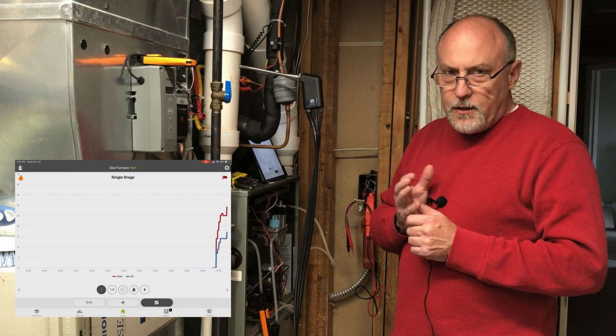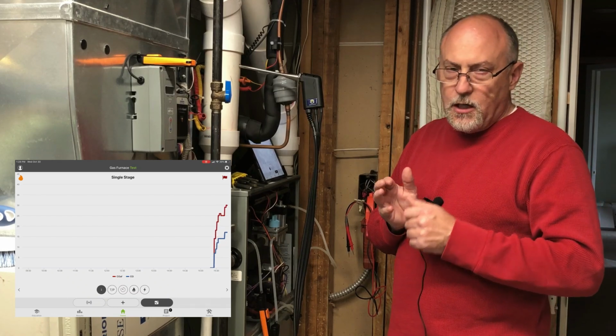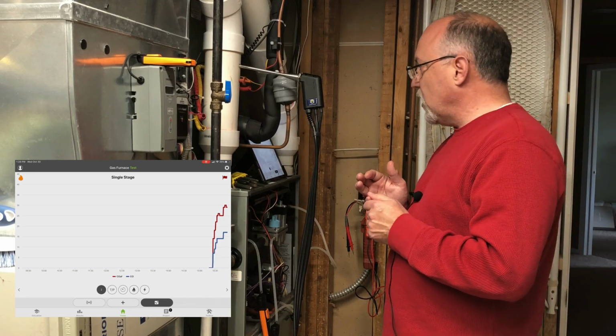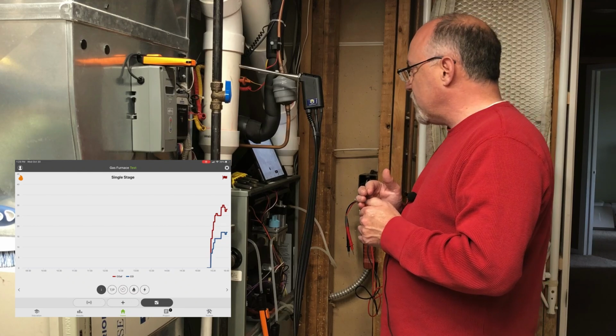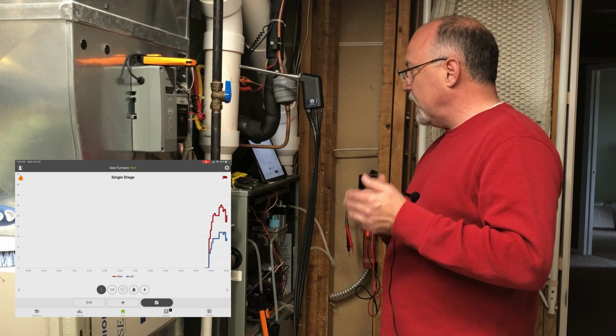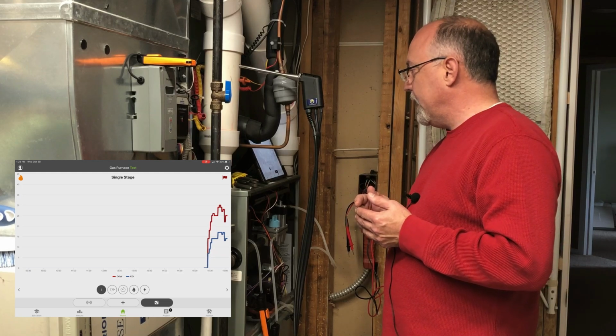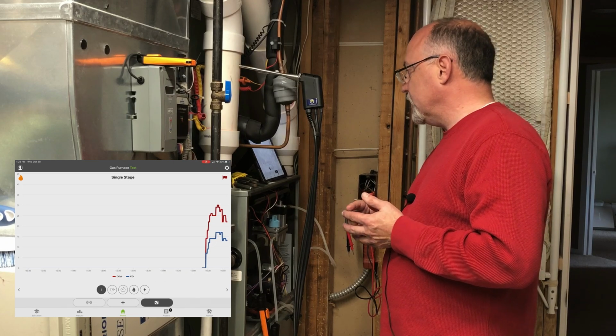CO air free takes into account your carbon monoxide and your oxygen. So if we have a decrease in oxygen or an increase in CO, we'll see that. So when it first lights off, it's going to be higher, and then it's going to sort of dip down. So we'll see that sort of stabilize. This one was already running, but as it runs here, we'll see where it stabilizes out at, and then we'll get an idea of when our combustion is stable, our analyzer is stable on there.